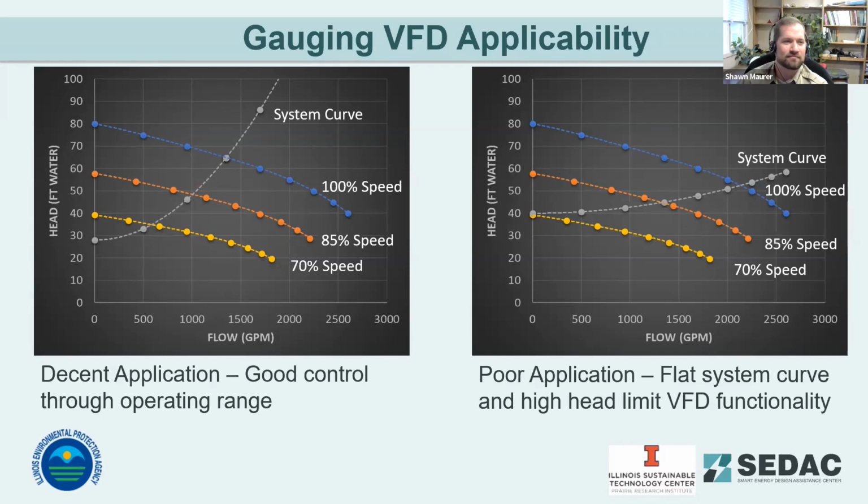So just something to touch on before we jump into the poll question. I want to launch that and make sure everyone's caught on to some of the talking points. Which of the below does not indicate a VFD is going to be a good application? Lower static head pressure, significant variation from the design point, flat system and pump curves, or longer run times. And then we did have a question coming into the chat: would a motor over 10 horsepower that runs over 2,000 hours a year be a good candidate for VFDs?